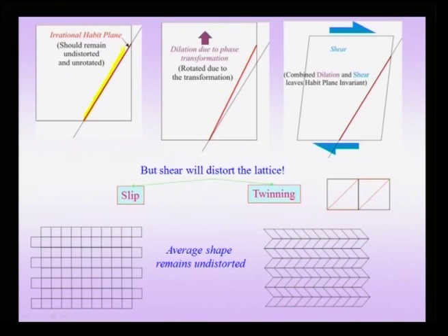Now, step 1, of course, is what we saw, some kind of a dilation or contraction, and let us consider dilation of this lattice. During this dilation you notice that this plane, which was originally present here, has gone to the new position, which is now marked in red. So, this is my new position of the plane. That means that now my plane, which was expected to remain exactly in the original place undistorted, has got distorted. In fact, it has got stretched, because the original length was A prime, and now the new position is A B prime, and A B prime is longer than A prime.